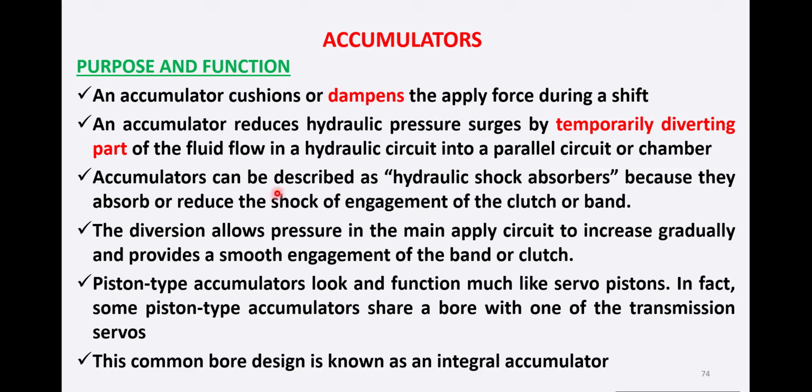The accumulator can be described as a hydraulic shock absorber because it absorbs or reduces the shock of engagement of the clutch or band. That's why we do not feel a jerk in the automatic transmission system as compared to the conventional transmission system.